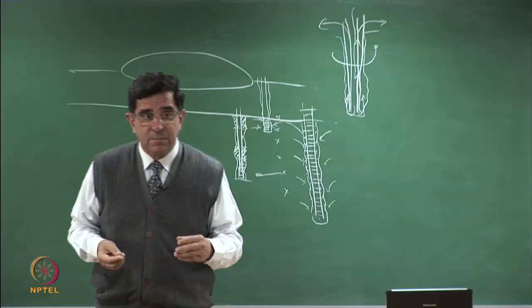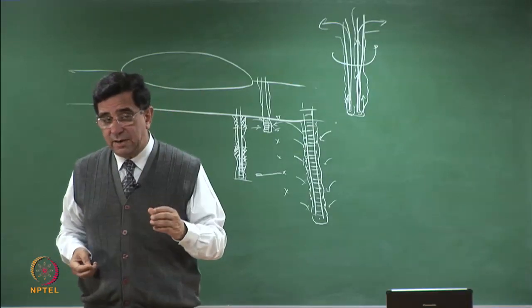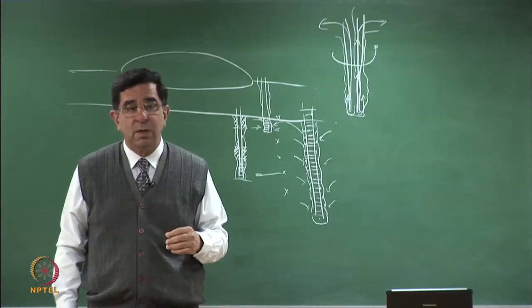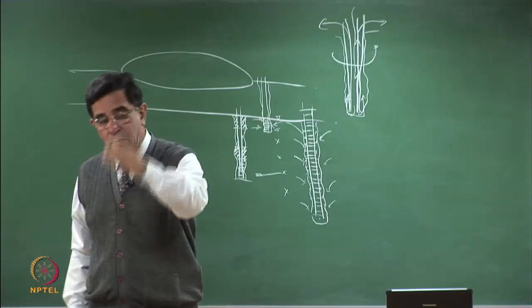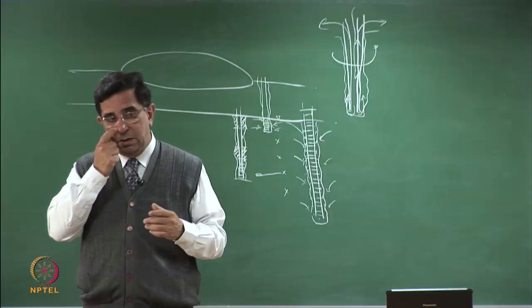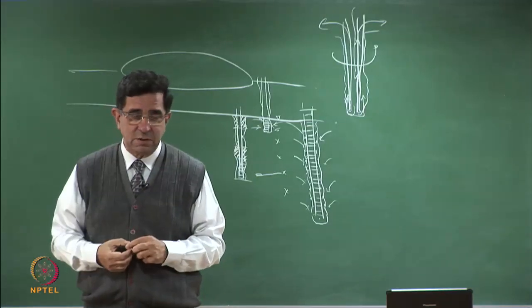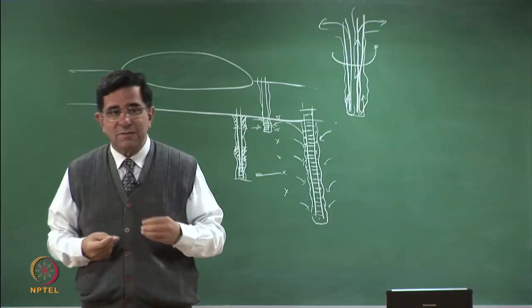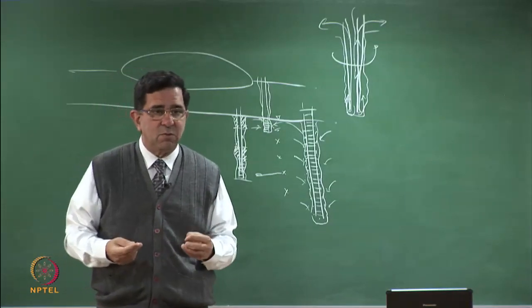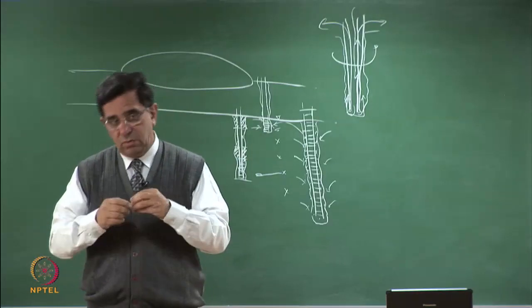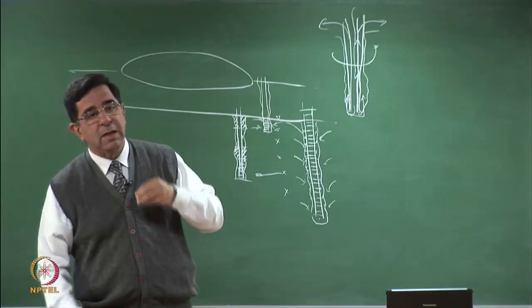So you will go to any landfill site and you will find, do you have a borehole for monitoring groundwater? Yes, sir. So there will be one borehole. Where is the water table? 15 meters deep. How deep is this? So this is 25 meters deep. But what are they sampling? Are they sampling from 15 meters or are they sampling from 25 meters or 20 meters? It's all mixed. Okay, you can have even a deeper well.